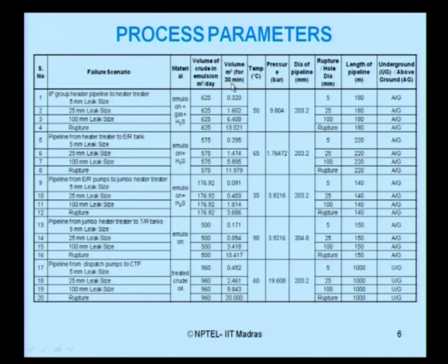Because in case of any rupture, I am using a manual control system, and it will take about 30 minutes for me to control that rupture. So, I am looking for what is the volume of transfer through a 5 mm leak for about 30 minutes. If I know the volume of transfer happening in cubic meter for 24 hours, I can find that out very easily. I already know the operating temperature of this specific liquid being transported is 50 degrees Celsius